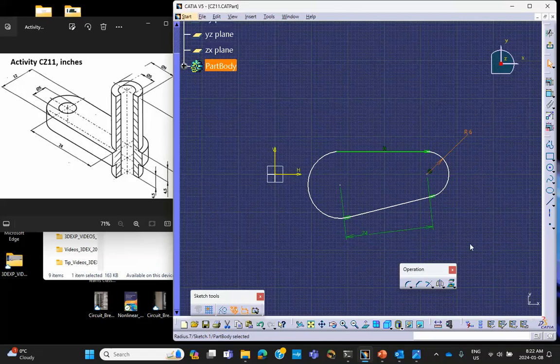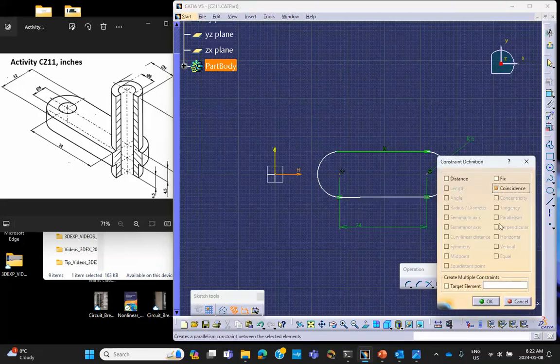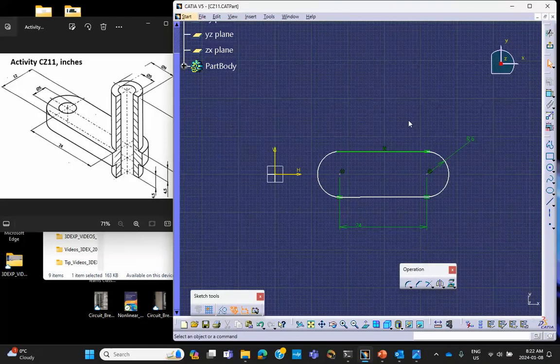All right. Now, the reason that happened is that this point is not on that axis. So let's clean it up. There are different ways of fixing it. You can make this thing horizontal, or you can put this point on that axis. So this point and that line, you make it coincident also. Okay, good.